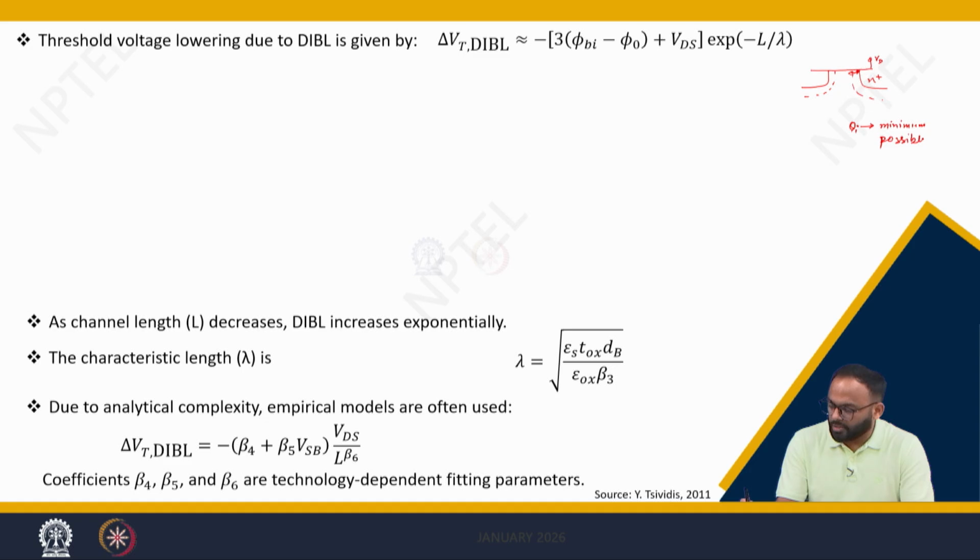because Vd achieves its saturation value or maximum value, and hence to maintain a constant current, the product of Qi dash and Vd max will adjust itself such that Qi will go to its minimum possible value.